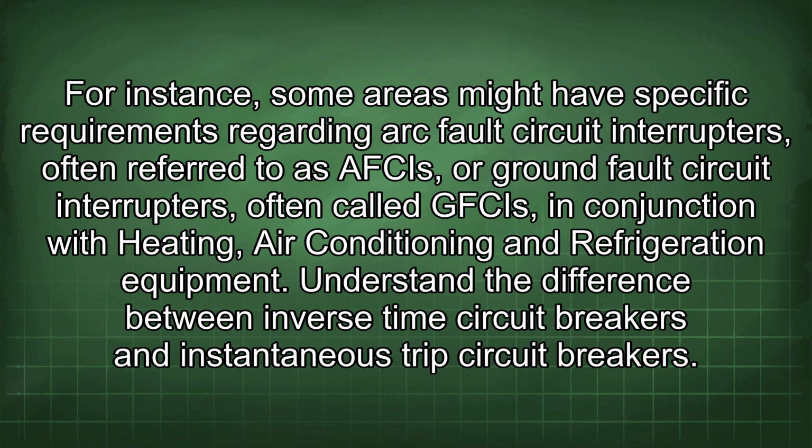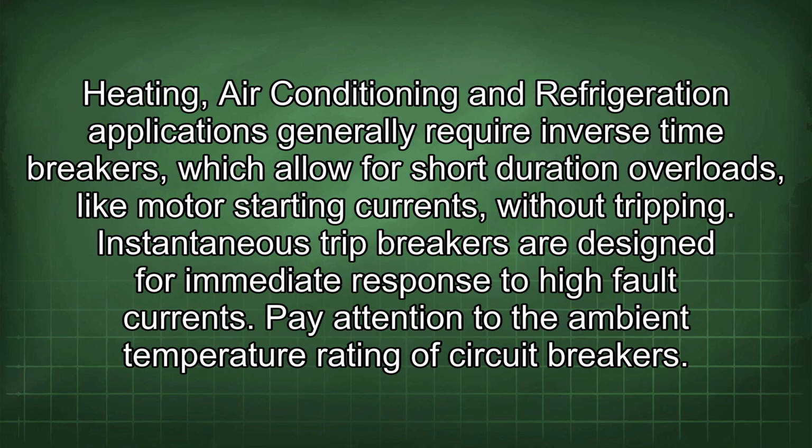Understand the difference between inverse time circuit breakers and instantaneous trip circuit breakers. Heating, air conditioning and refrigeration applications generally require inverse time breakers, which allow for short duration overloads like motor starting currents without tripping. Instantaneous trip breakers are designed for immediate response to high fault currents. Pay attention to the ambient temperature rating of circuit breakers.